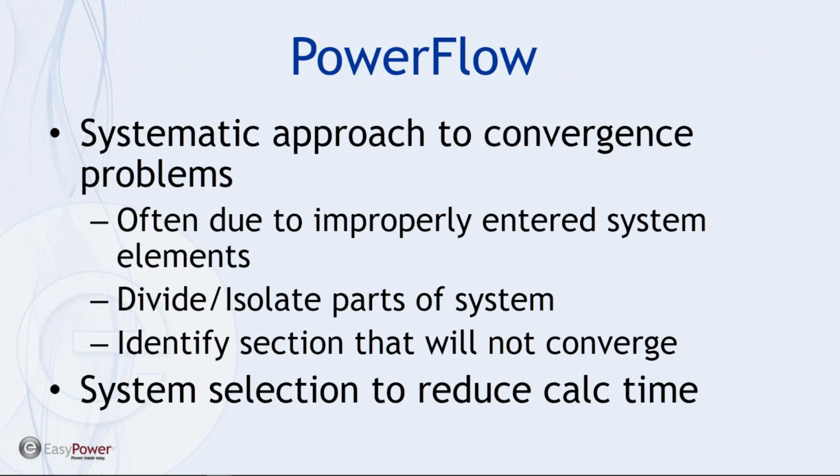So what we're going to be talking about is essentially a systematic approach to convergence, and what you find when you start to do PowerFlow analysis on some systems is that it can get thrown out of whack because some system elements have been improperly set up. Consequently, the PowerFlow module itself is a good debug tool in terms of identifying anomalies in our database initially, when we're doing data collection for a short-circuit or ArcFlash study.